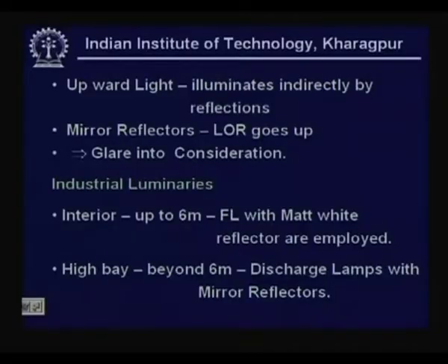Whereas, what we call high bay luminaires are used whenever there is height beyond 6 meters, and there invariably it is the discharge lamps. We have already mentioned discharge lamps are used on two accounts. One, because they operate with high luminous efficacy.